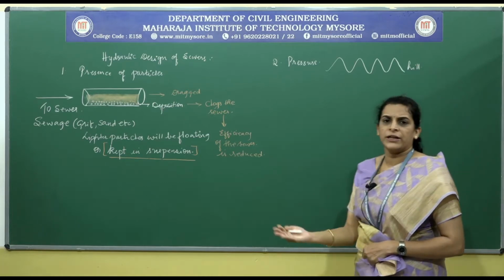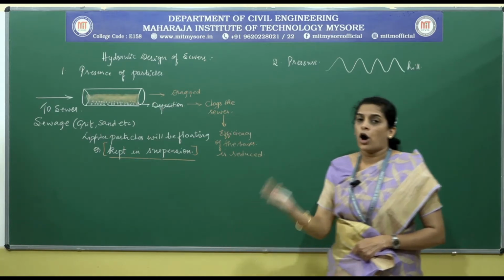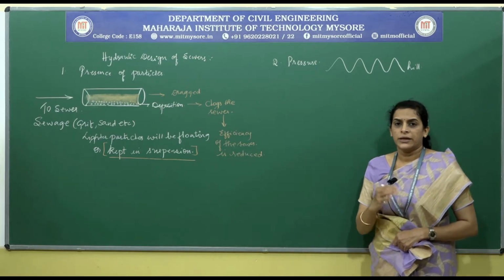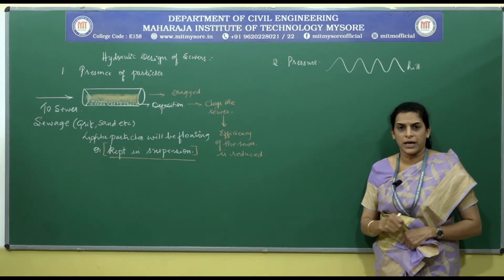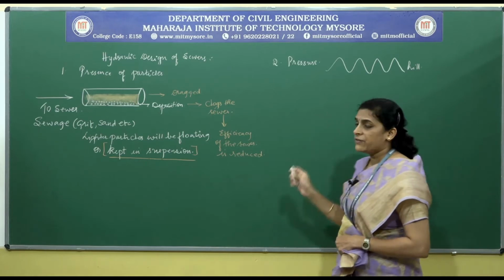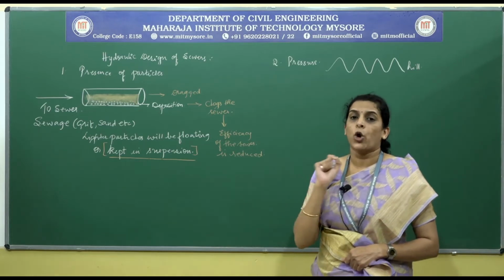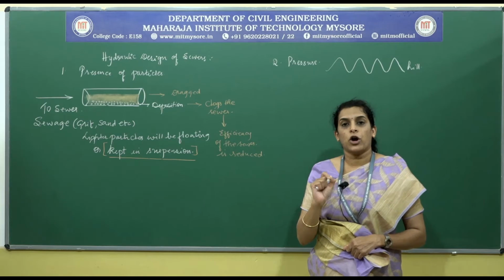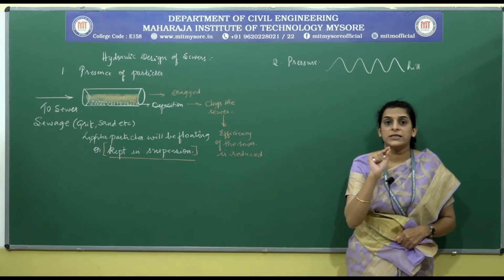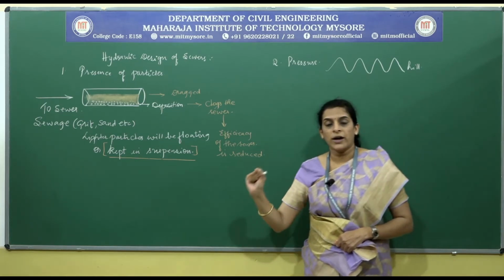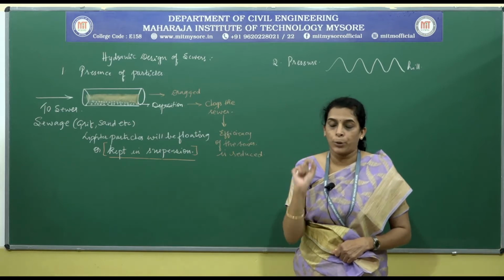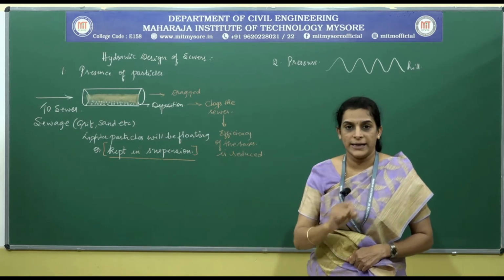There may be a gravity flow, pumping, or a combination of that. The dual system may even be there, while the sewer is considered as an open channel, because there the sewage is led in the downward direction by providing a proper gradient.